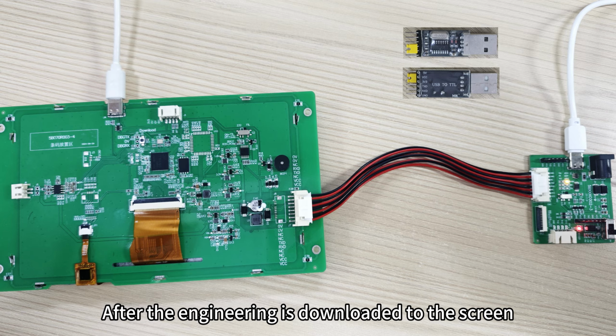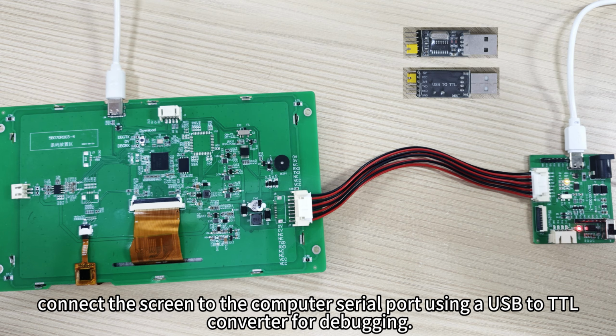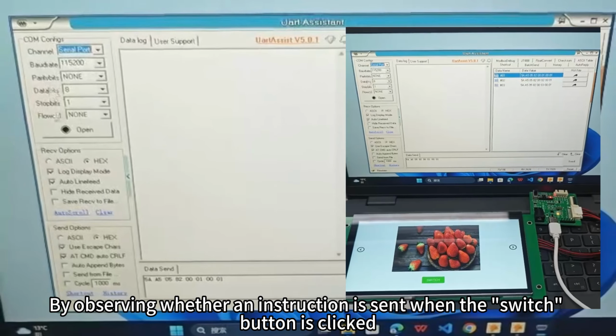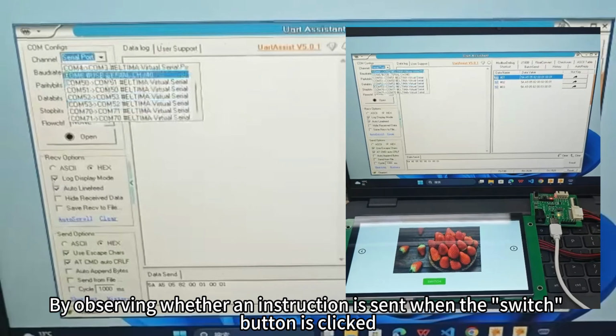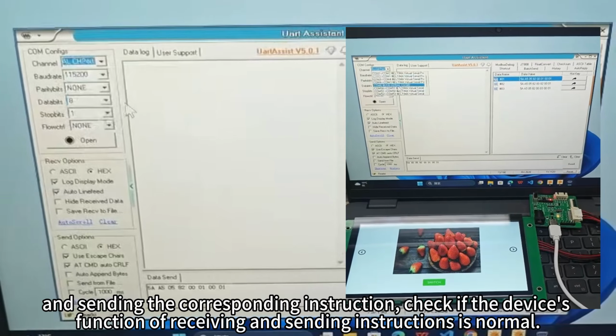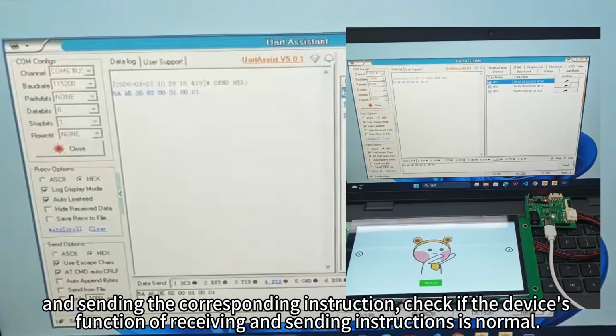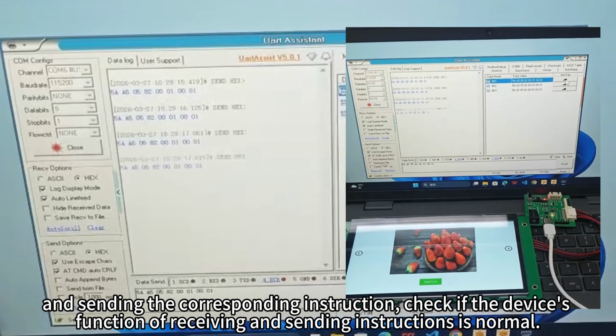After the project is downloaded to the screen, connect the screen to the computer serial port using a USB to TTL converter for debugging. Use the computer debugging software to simulate the client host. By observing whether an instruction is sent when the switch button is clicked, and sending the corresponding instruction, check if the device's function of receiving and sending instructions is normal.